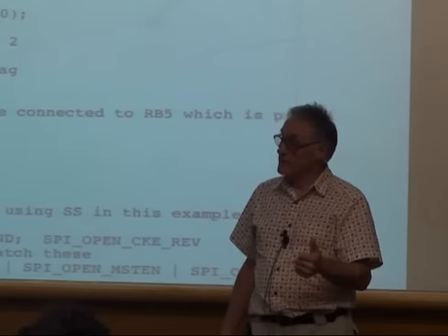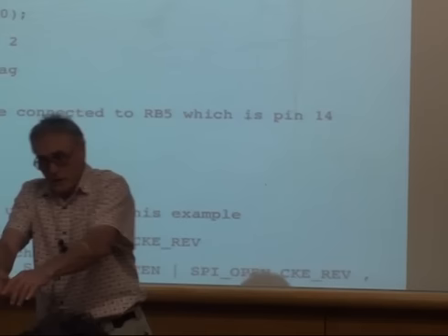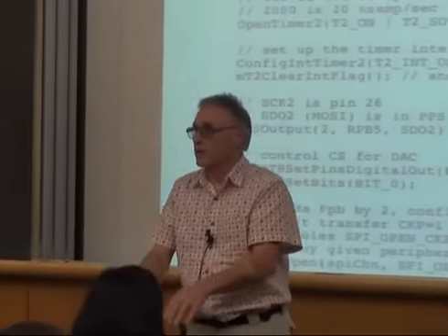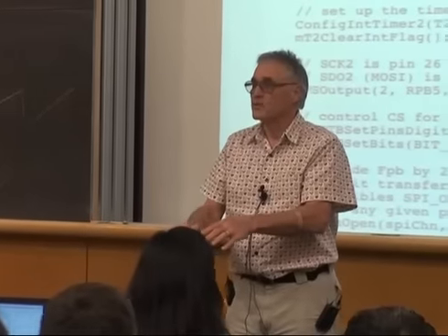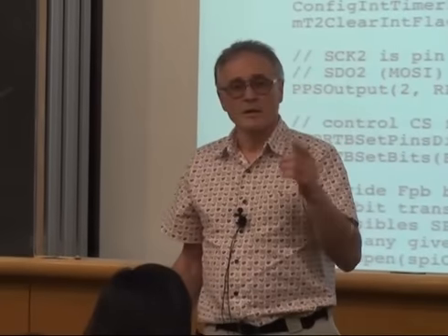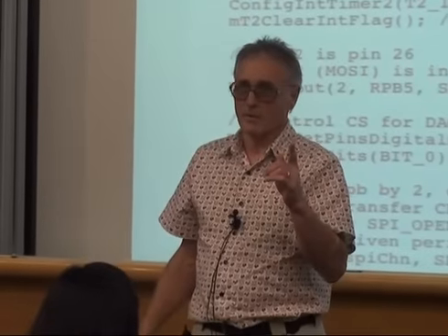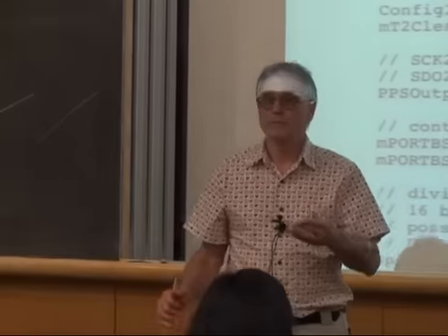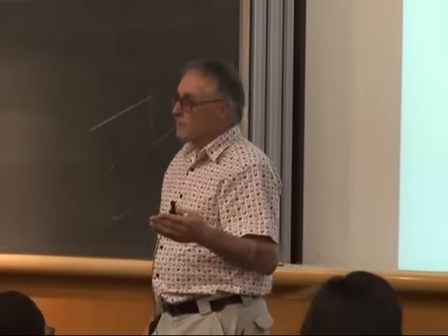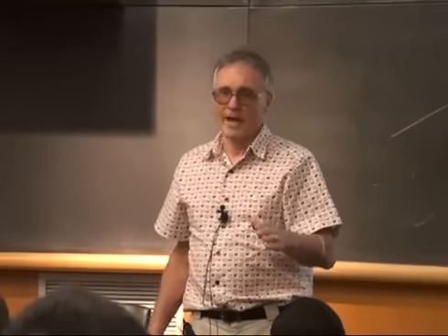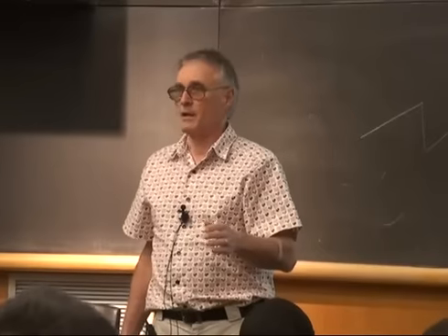Don't wait. Do not. I've seen this happen before. One person in the group does the keypad scanner. Yeah, I got the state machines ready to go. The other person in the group is cranking away doing the direct digital synthesis stuff. The day it's due, they merge the two codes. And it fails. Because, inevitably, some variable is shared, or a piece of memory is corrupted because of name overlap. If you want to modularize things and work on it separately, that's a good scheme, but don't wait till the last day to merge the codes.